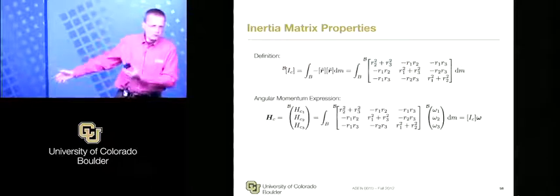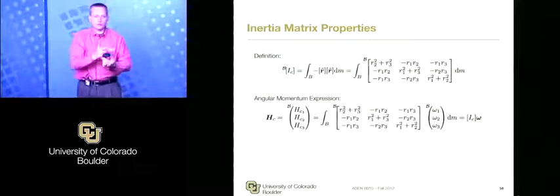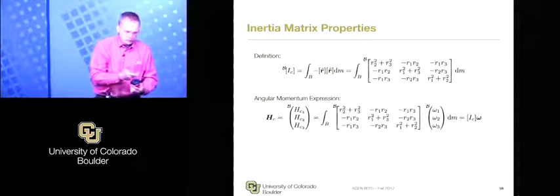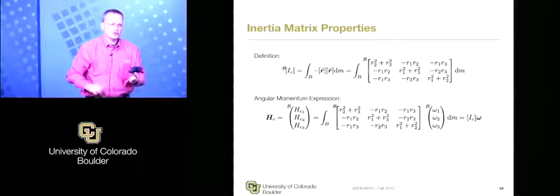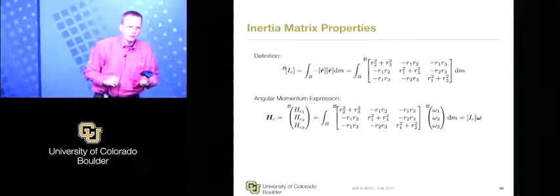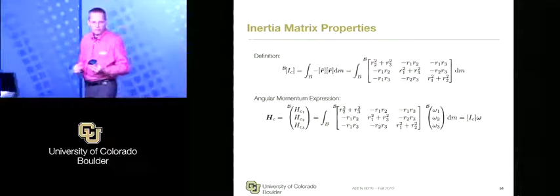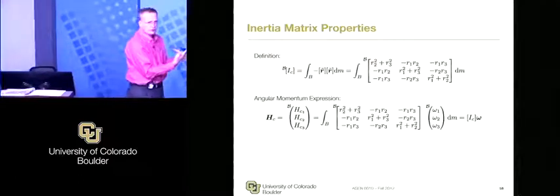And often in analysis we make that assumption, because for any rigid body we can always pick a coordinate frame where that's true. Are the principal axes unique, Benjamin? Is there only one set of principal axes for something that has 3 distinct inertias? I would say no. Okay. If this is one set of principal axes, what's the other set then?